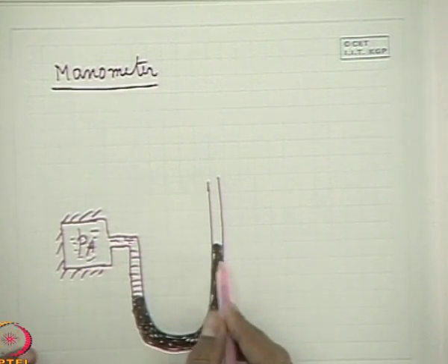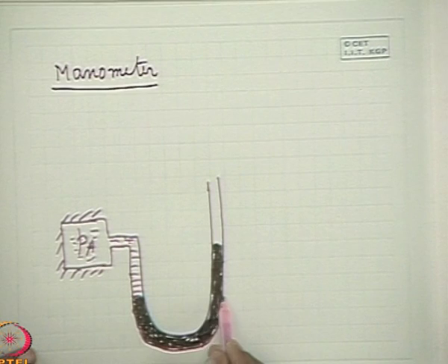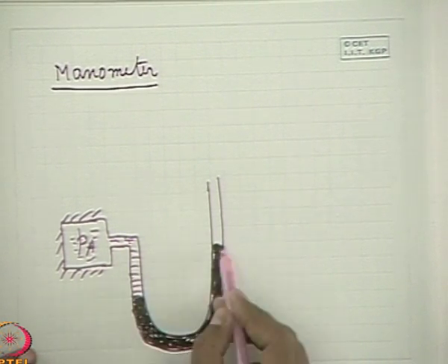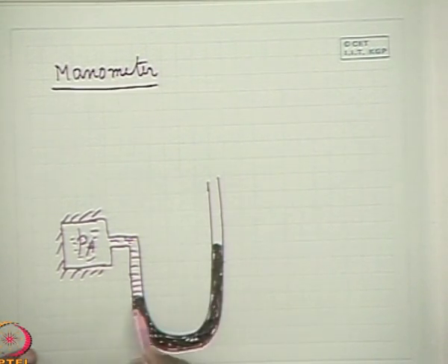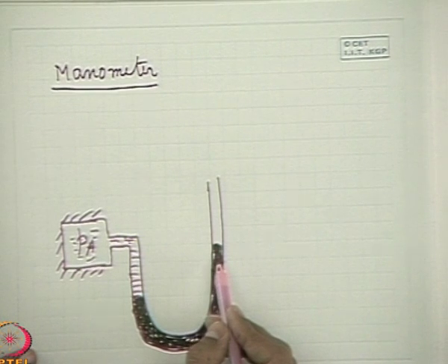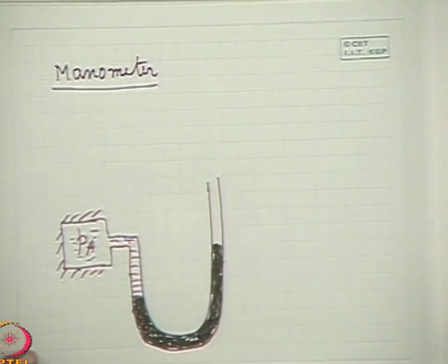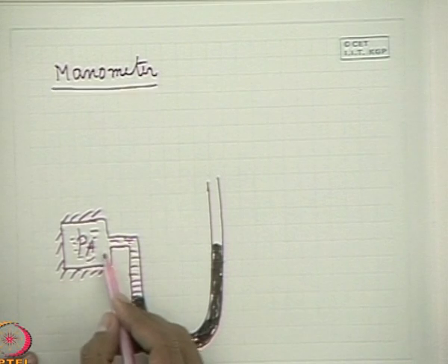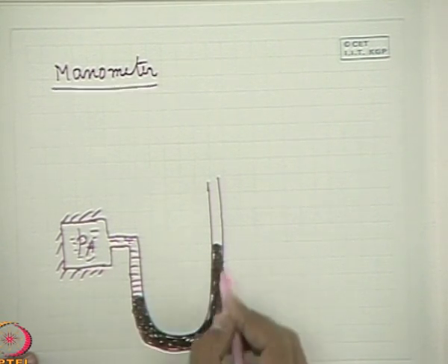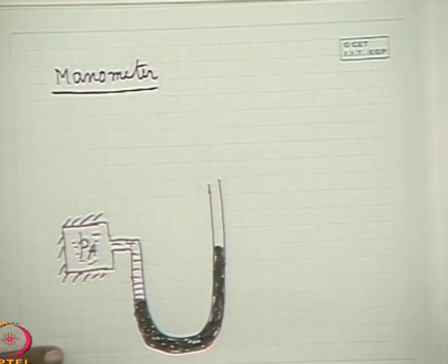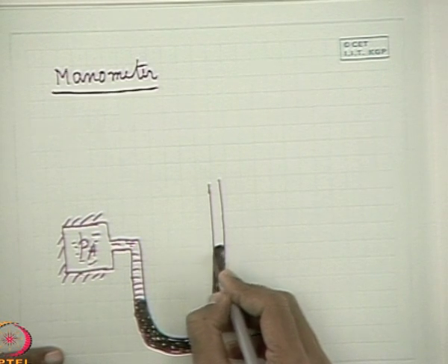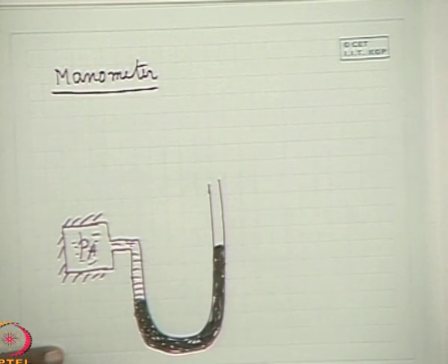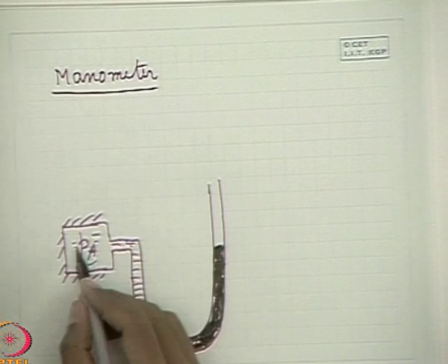Usually if you fill a tube with any liquid, they will fill up to the same height, because the pressure on both sides will be the same and neither side can have a higher or lower vertical displacement with respect to the other. But when this pressure is more, the liquid will be displaced like this. And this fluid obviously will have a higher density than the system fluid.